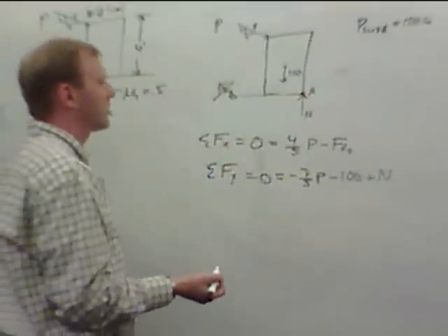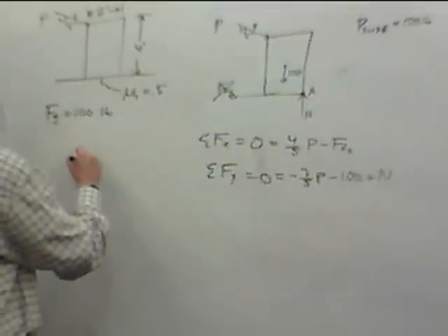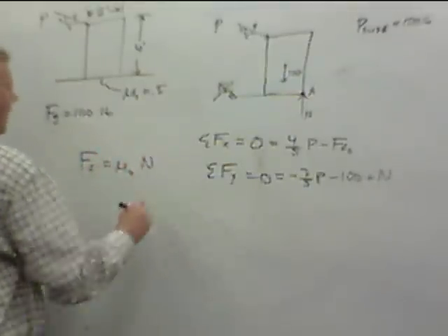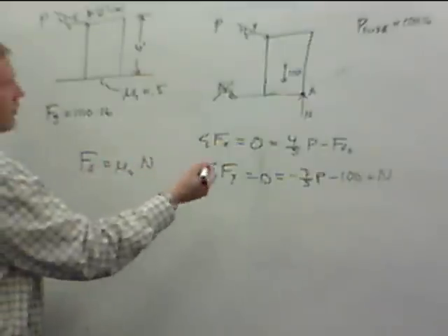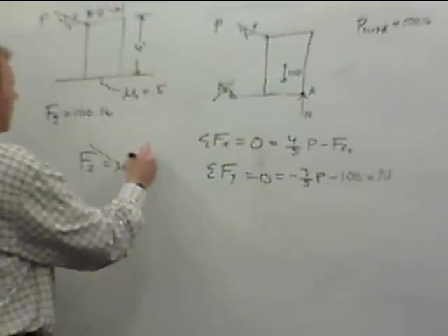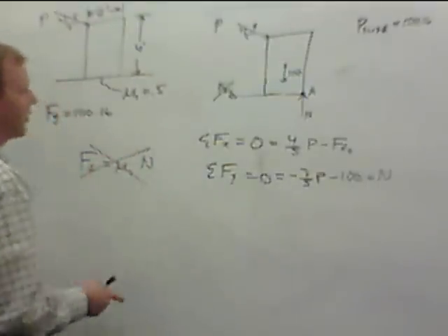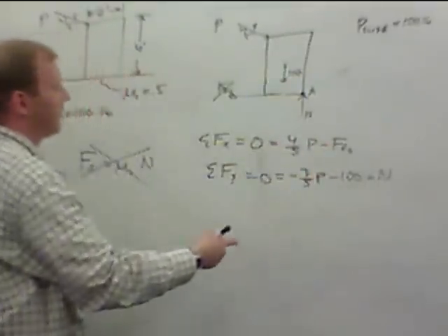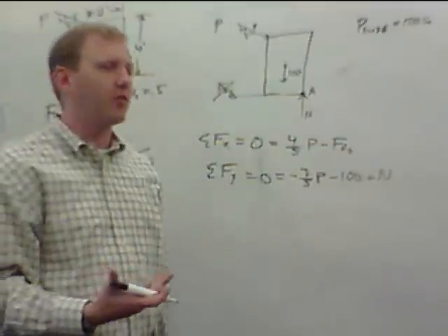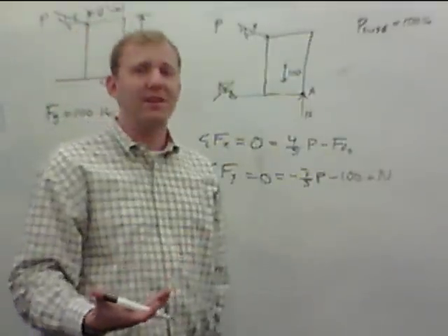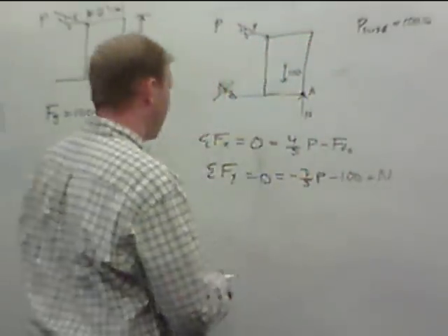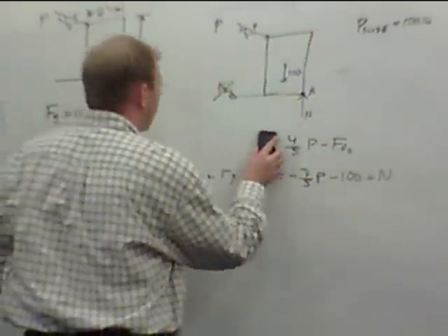When we were talking about sliding, we could use force of friction equals mu s N, because they were equal when something was about to start sliding. When we're just dealing with something that's about to start tipping, we lose that third equation. We can't solve this system. We can't solve a tipping problem with just analysis of forces, which makes sense. For tipping, we're rotating. That means we probably have to factor in the moment. So that's what we'll do here.